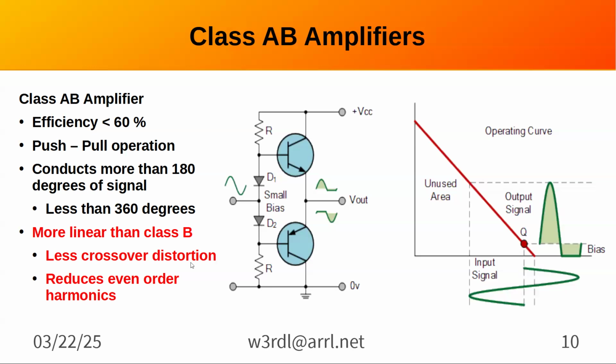Was there another bullet down there? No. So depending on how much this bias offset is will determine how far it conducts on the other half of the cycle. Move that little black thing there, so you can see the input. It's the same, it's just the sign. And they're only showing one of the transistors on the output.